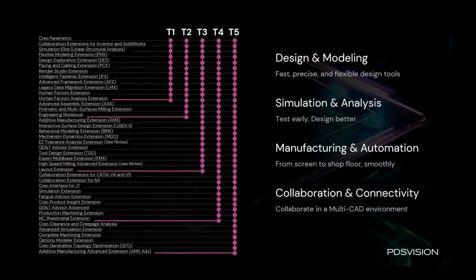Can behavioral modeling be used with simulation? Yes, so you can tie the behavioral modeling, which is the application where we talk about providing your design with some parameters and having Creo optimize for that solution. That can be tailored with simulation, yes. So either you're using Creo Simulate Live, our ANSYS powered product, you can leverage maybe simulation probes, stresses, deformations, and have that drive maybe a dimension.